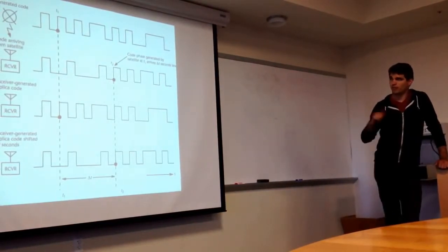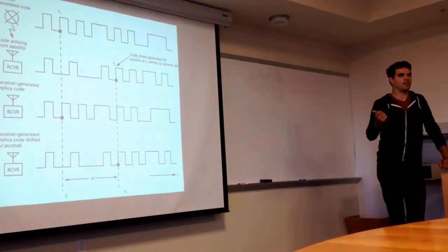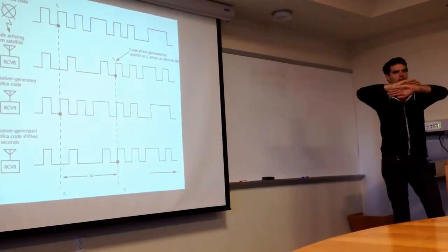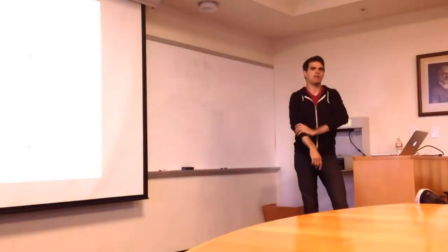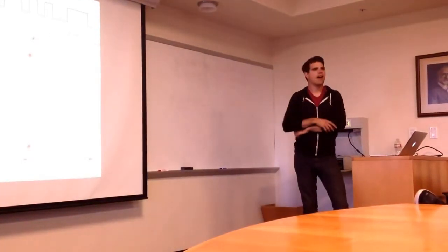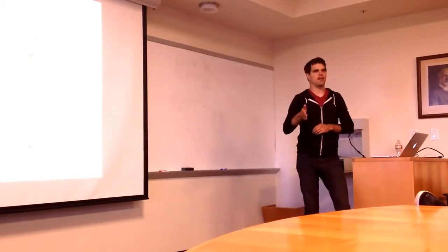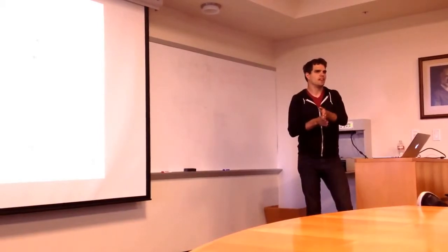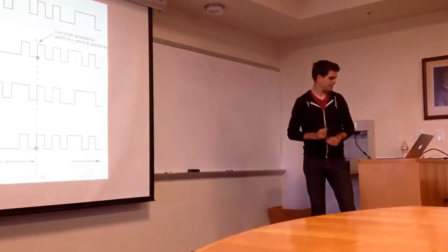So that's basically what GPS receivers do. They locally generate this pseudo-random string. They swoop it through the received signals until they find where it lines up. And you know where it lines up by seeing a huge amount of increase in the power coming out of your receiver. And now you say, cool, the signal I'm generating is starting at the same place as the signal being received from the satellite. And now, great, now my timer is running, and now I say, okay, I just received the signal, here's the start of it. How long did that take to get here?